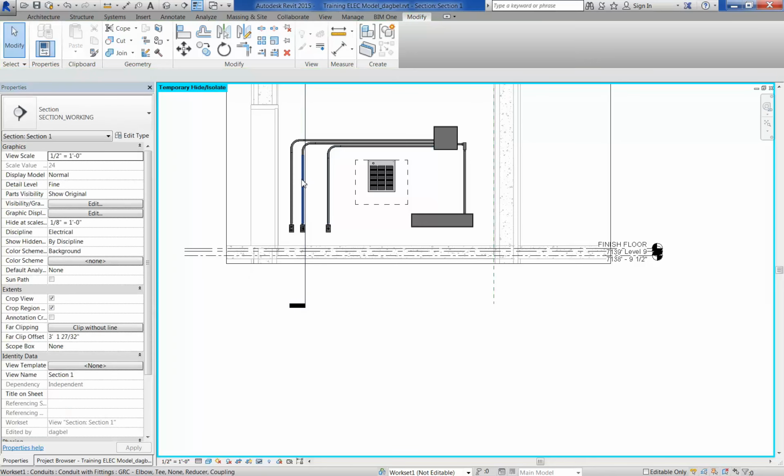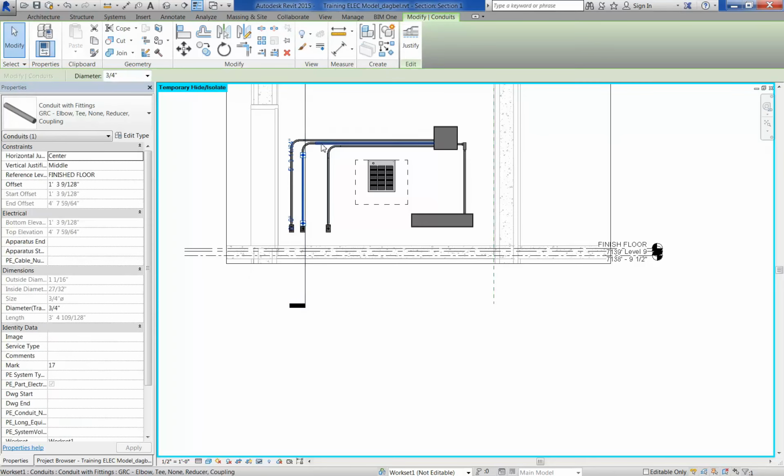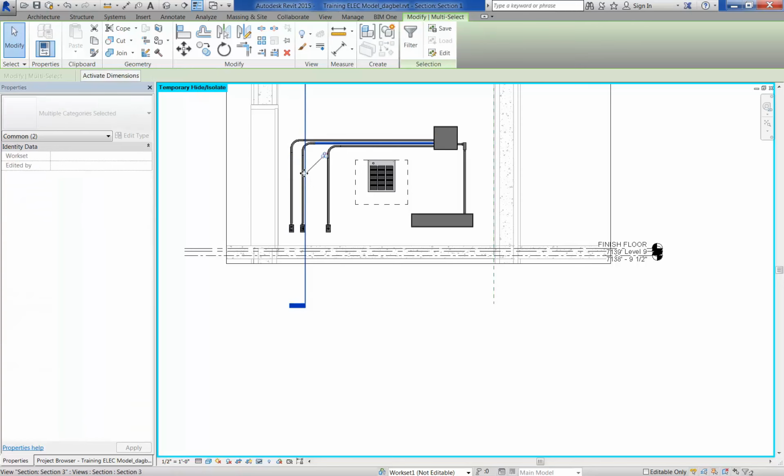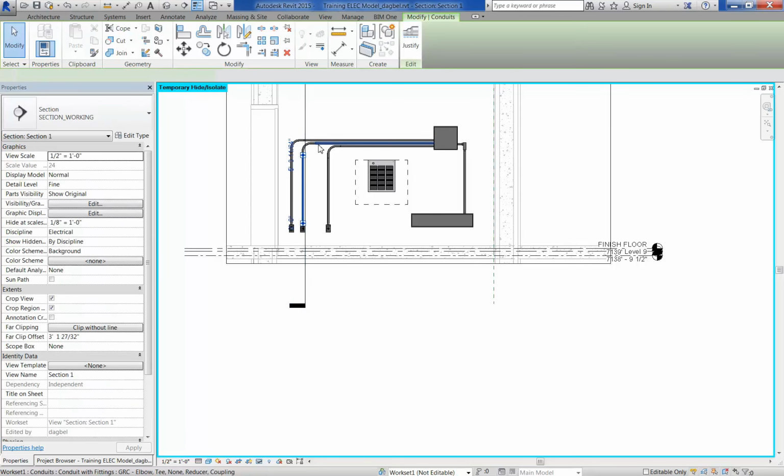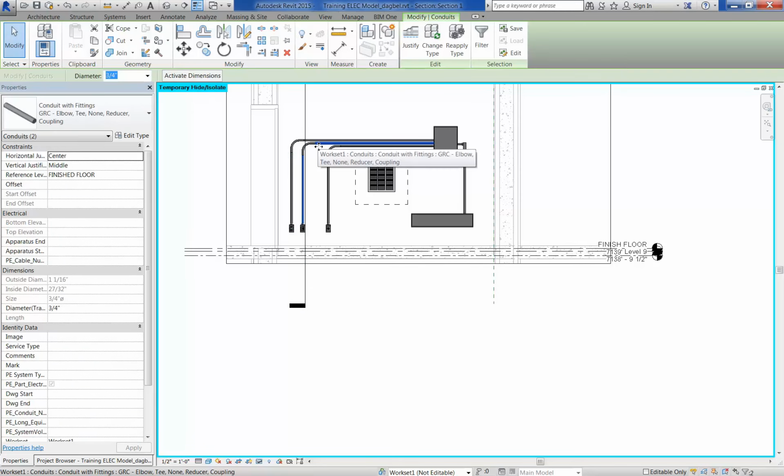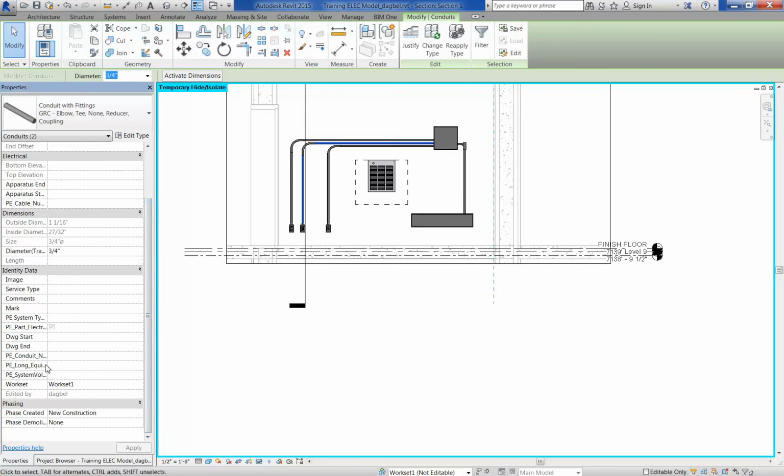And the conduit schedule schedules only the straight pieces of conduit. It's really unnecessary to go ahead and schedule the fittings. In fact, as we've seen here, Revit will redraw your fittings if you break the conduit at some point. So numbering and putting information in for the fittings can be a waste of time if you end up having to do any conduit rework.